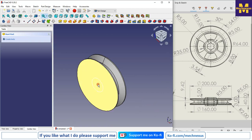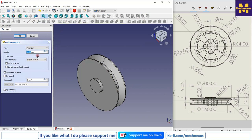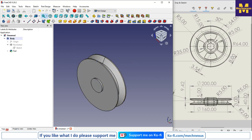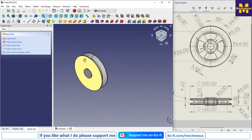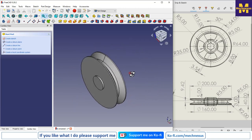and now we will go with the pad, and we will add the pad of 5 mm. Say OK, and the same pad we will make on the other side with the help of the mirror tool. So I will select the features and click on the mirror, and you can see that the pad has been added here. So I will go here and click on select reference, and I will select my reference, which is the XY plane. We'll say OK. So now we will rotate it, so the feature has been patterned.